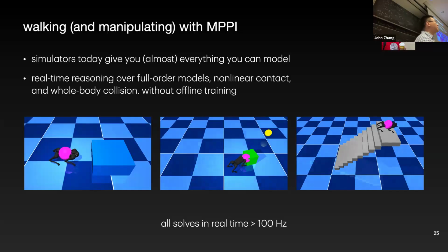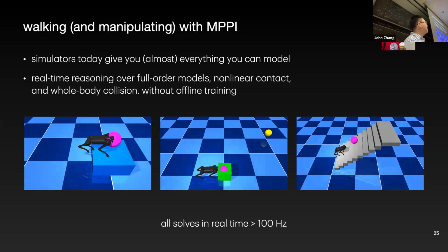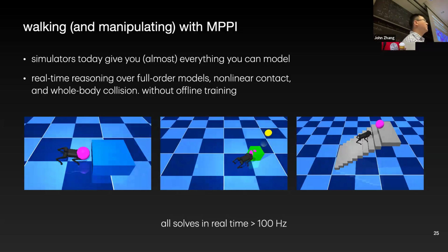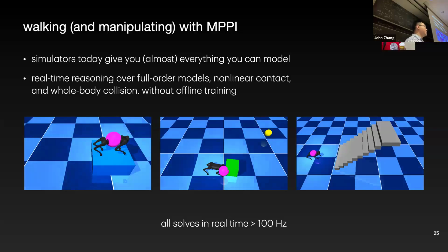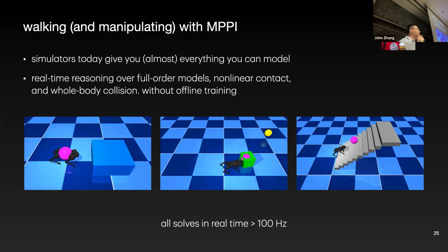The behavior that MPPI can perform is limited by the horizon which we are rolling out, right? I'm assuming you can't back it, because for that you need a way longer horizon rollout. Sorry, which task are you discussing? Just using MPPI, we can't apply it everywhere, right? Right. It's still a local optimizer. It's a little weird in the sense that it explores multiple local minima before converging to one of them. In the limit of infinite horizon, it does a sort of global search, but I still consider MPPI a local method.